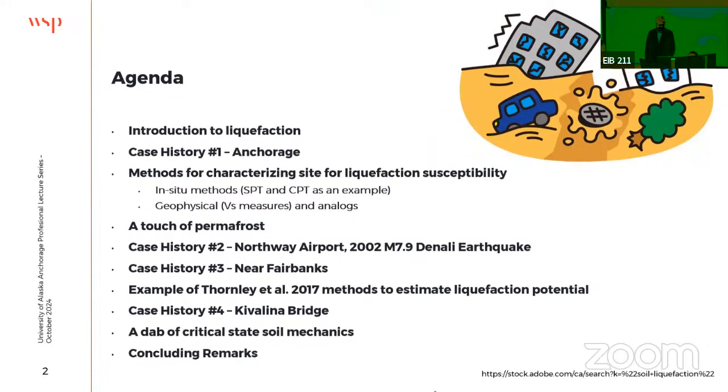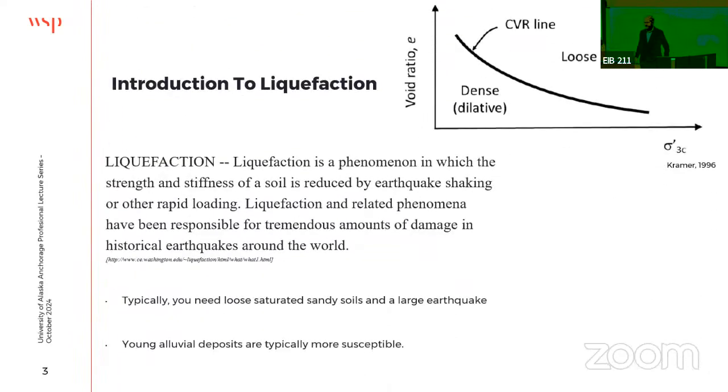Next slide. Sure, next slide. All right, so introduction to liquefaction. Does everybody know what liquefaction is? All right, so it's essentially a strength loss due to ground shaking. Effective stresses go down and there is loss of strength. Typically you have loose saturated sandy soil and an earthquake, and oftentimes this happens in younger alluvial soils that haven't been consolidated or densified as much, right? So this is the loose state that you're sitting in.